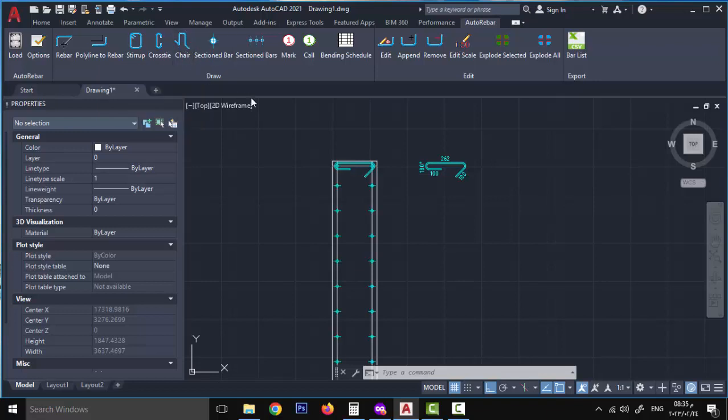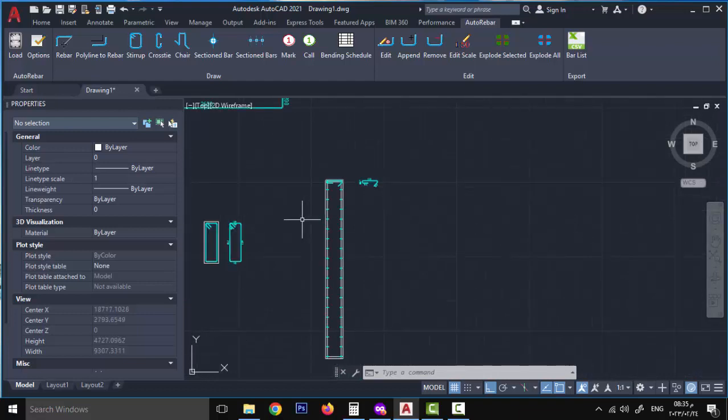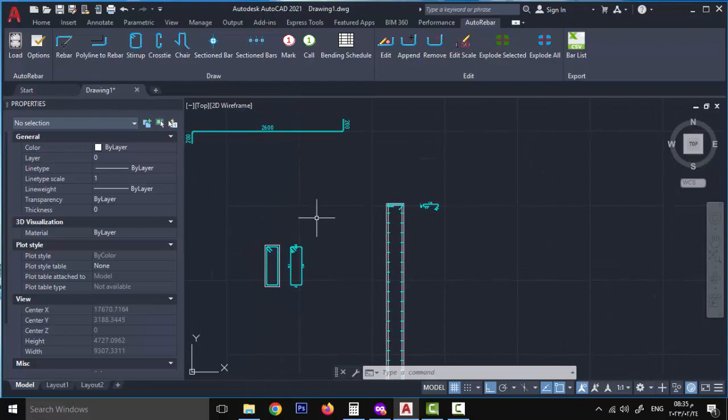The chair simply is a piece of rebar which is used to lift the top rebars. So let's assume you have a slab. The slab has bottom rebars and top rebars. The bottom rebars are simply lifted by cover, something that you can use to make cover. Let's say it is maybe a marble or granite or whatever, plastic maybe, but in order to lift your top rebars and make them in place, you have to use chairs.